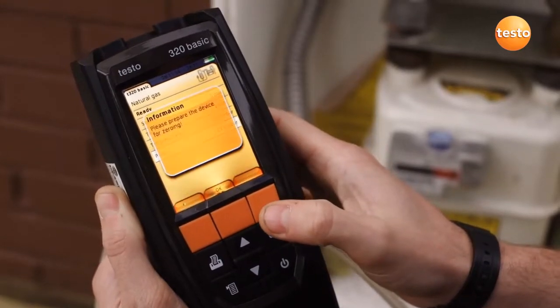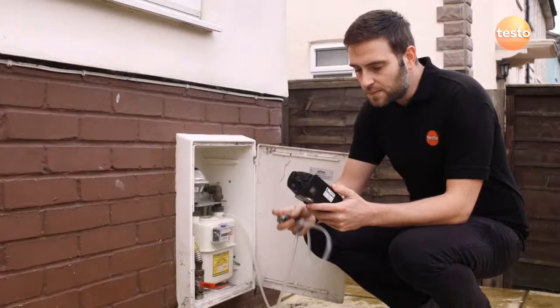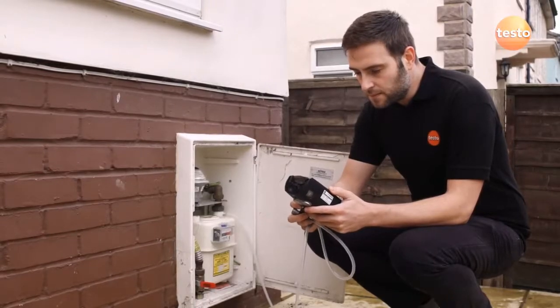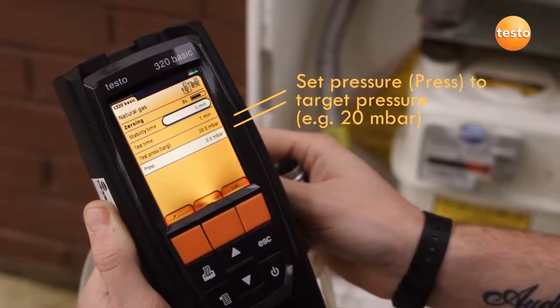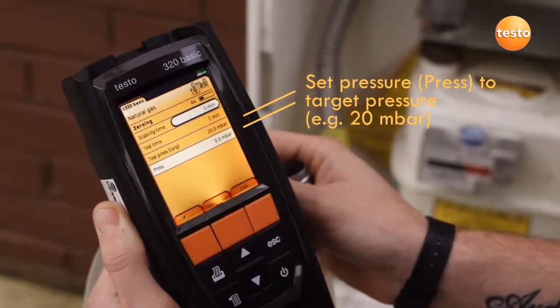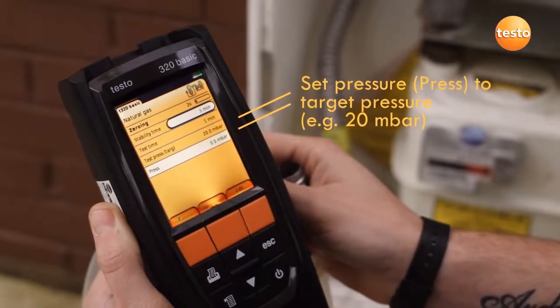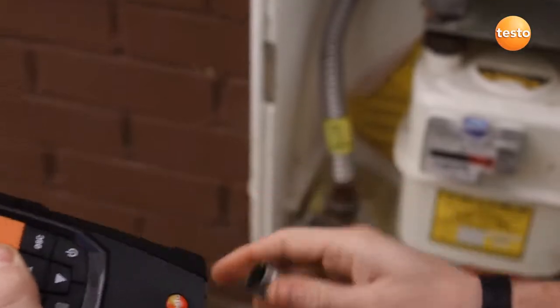The analyzer must be zeroed for the tightness test. Remove the pressure hose for zeroing, and then reconnect it afterwards. After zeroing, the 320B displays the tightness test with default settings which can be adjusted. In this case, the target pressure is 20 millibars, and the test is to check that the pressure doesn't drop, which would indicate a gas leak.